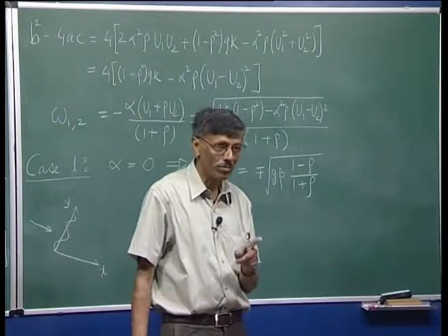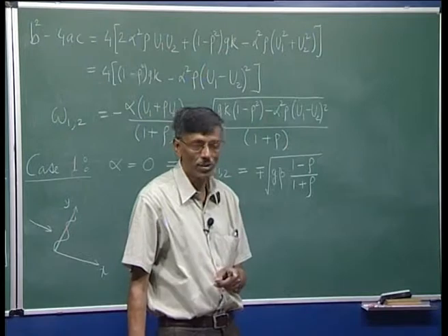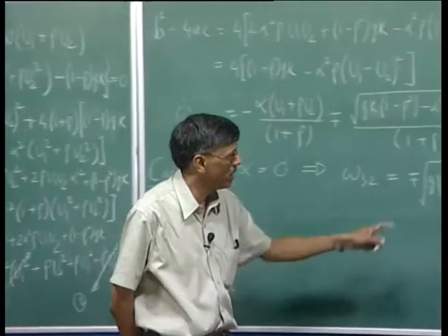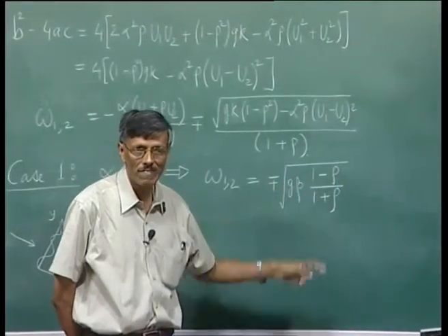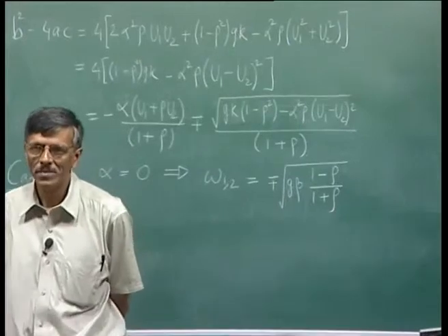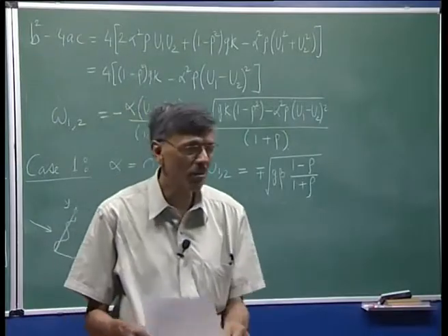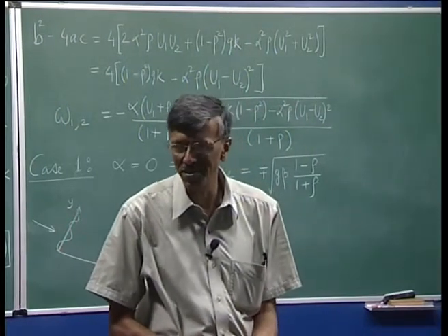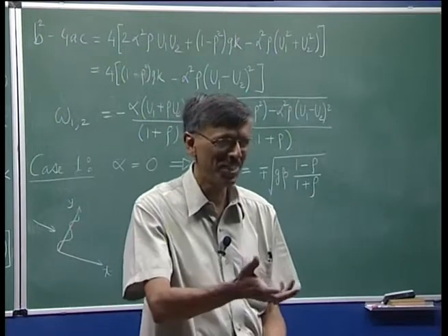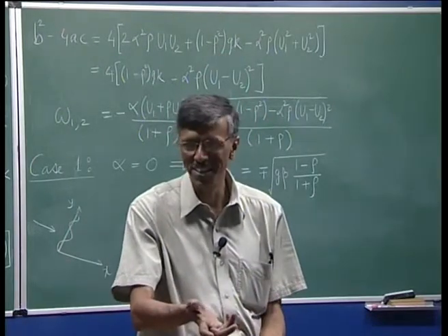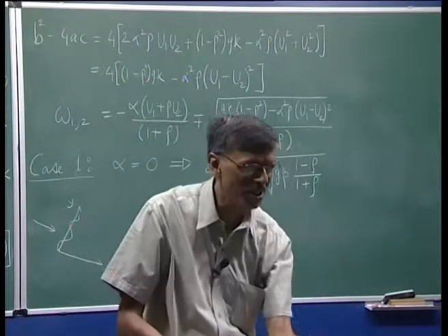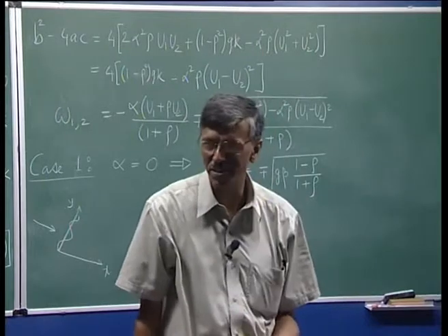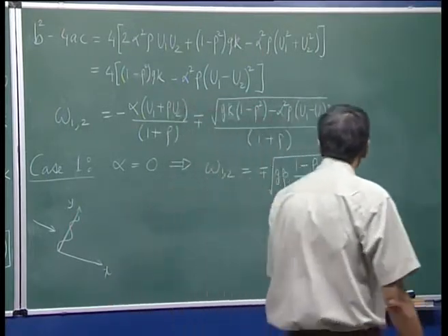Now, you have to think about what is rho. Rho was rho 2 by rho 1. So, you are going to have instability when this rho is greater than 1. That means what? A heavier liquid is resting over a lighter liquid, and common sense tells us that is going to be unstable. If I try to do that anywhere, even with a rigid body, if I try to balance a heavier object on top of a lighter object, that has a tendency to fall. Fluid also shows the same thing. This indicates instability